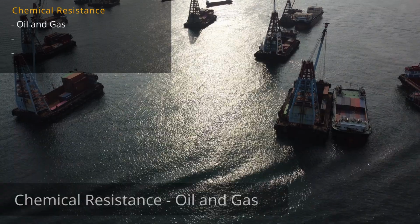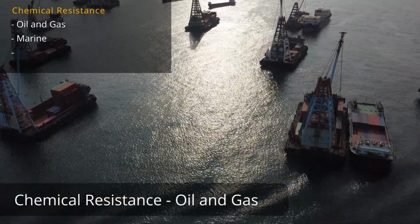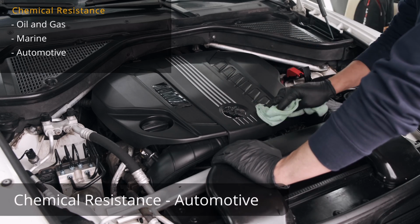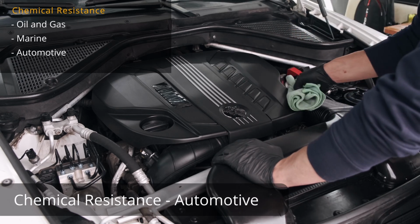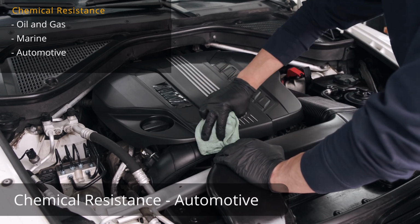So you have, say, oil and gas, you have marine environment, and even in automotive, where, for example, you will have an engine bay where you have a lot of chemicals in there and you want the components in there to have longevity for the lifetime of a car. And as you can imagine, thermoset composites perform very well there. And they perform very well because the materials cross-link, therefore very stable. Whereas thermoplastic composites, the answer to that really depends.